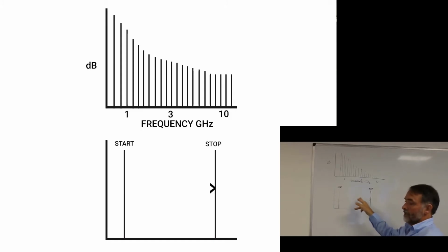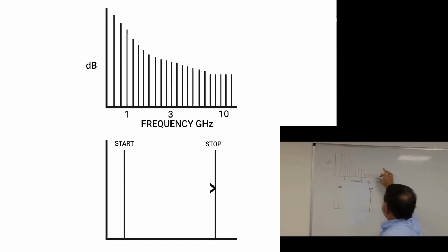What the VNA is going to do is this. It's going to put out 10 megahertz, and then in a sequence of steps, it's going to put out each frequency all the way, in our case, up to 6 gigahertz on the VNA. The benefit of this is, with the step, you really haven't got much signal available at high frequency.